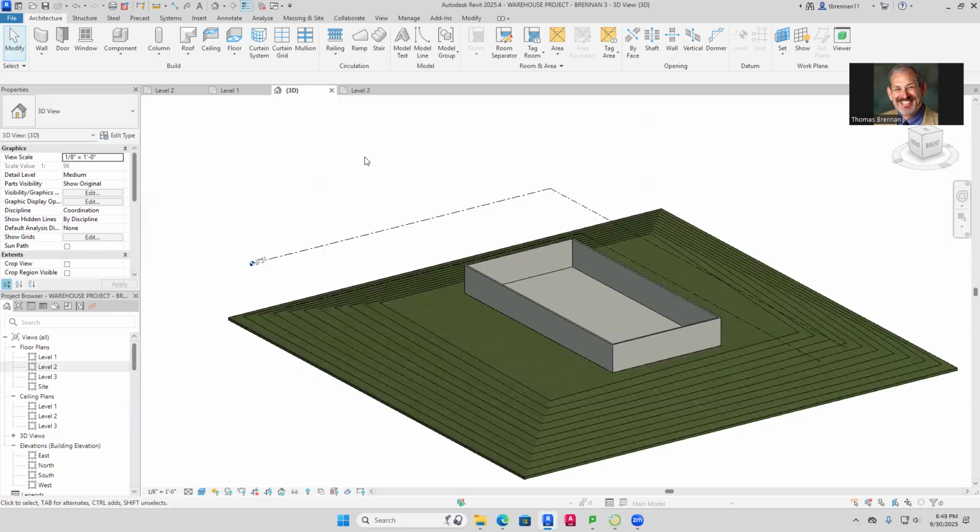you want to put in your walls, your interior walls. What you want to do is create 2 restrooms with toilets and sinks. The reason I'm telling you this is because if you don't put your interior elements in first, you're going to have to go a lot of back and forth. So it's just easier to do it that way. You're going to use the interior walls for your partitions, 5.5-inch walls for the interior. You want to do that.